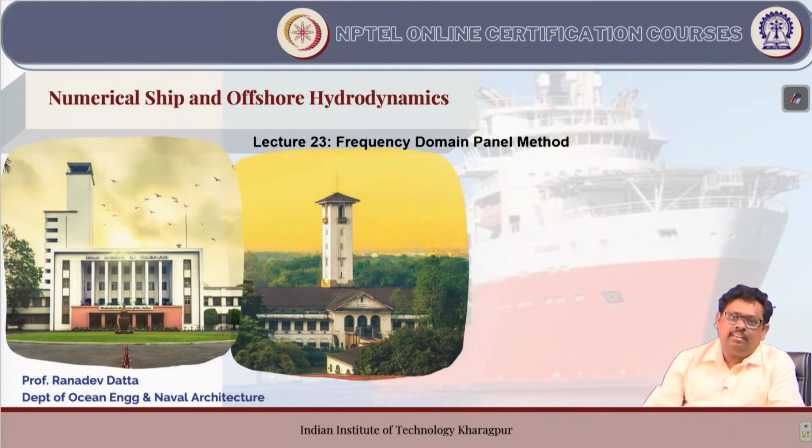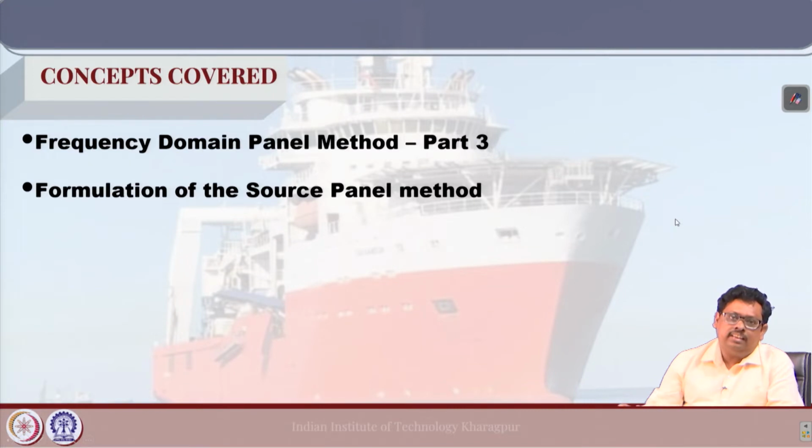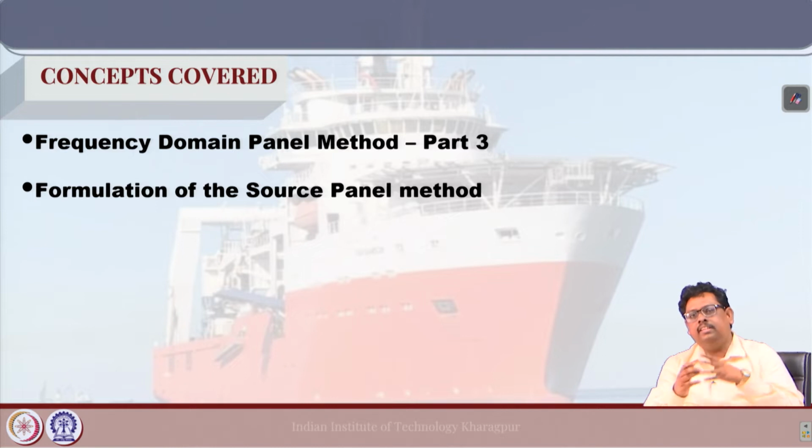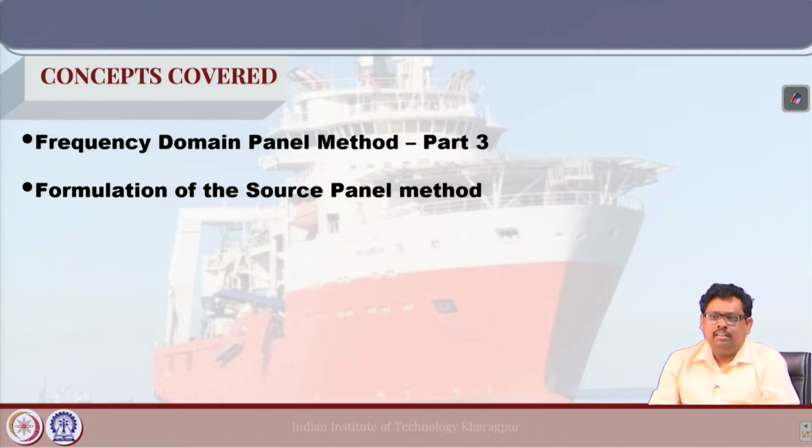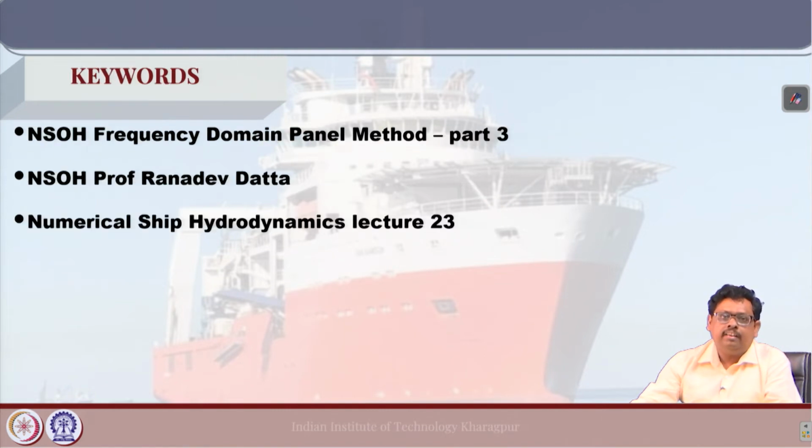Today we are going to discuss the formulation of the source panel method. If you remember, in the last class I said there are three different kinds of panel method based on the discretization. One is source dipole, that we have solved for the infinite fluid domain, then the source panel method, and another one is the dipole panel. Let us see what the other methods are here.